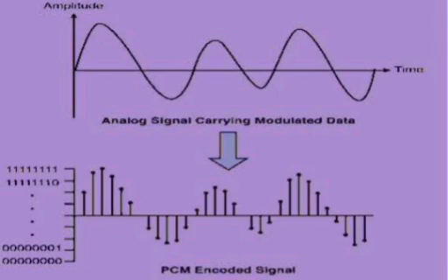Error control codes. When a signal is transmitted through a channel, the probability of error for a particular signaling scheme is a function of signal to noise ratio at the receiver input and information rate. In practical systems, maximum signal power, the bandwidth of the channel, and noise power spectral density eta by 2 are fixed for a particular environment using a signaling scheme. It is often not possible to achieve an acceptable probability of error. Therefore, error control coding is used to achieve the required minimum probability of error.